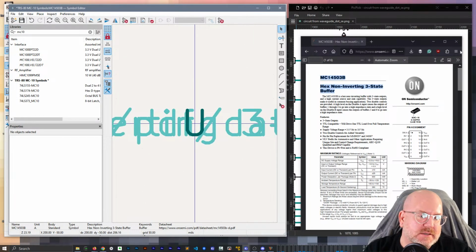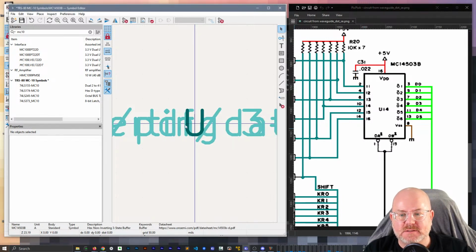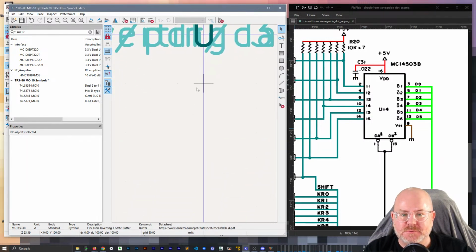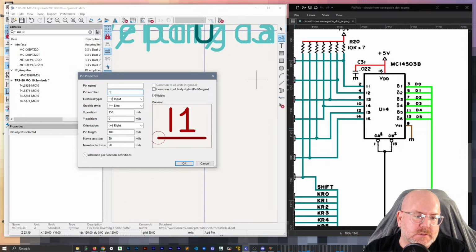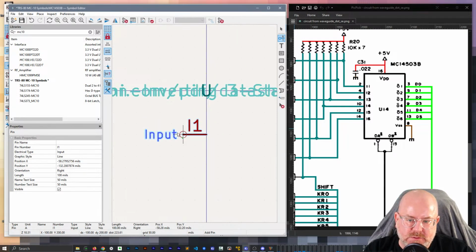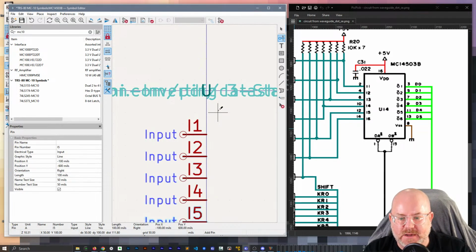Okay. So then, how did they draw? So let's see, we got I 1, 2, 3, 4, 5, 6, 7, 8, output 1, 2, 3, 4, 5, 6. Yeah, so we'll do this. We kind of did this the other day. We'll do it the same way. We're going to use the insert trick. So I'm going to just do pin number, which is I1. This is input, so that's easy. The output I'm going to assume is tri-statable. So now I'll hit insert to get 2, 3, 4, 5, and 6.